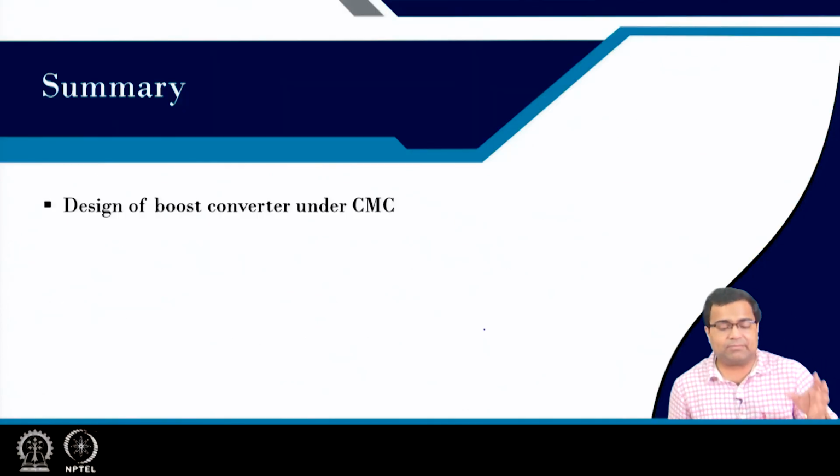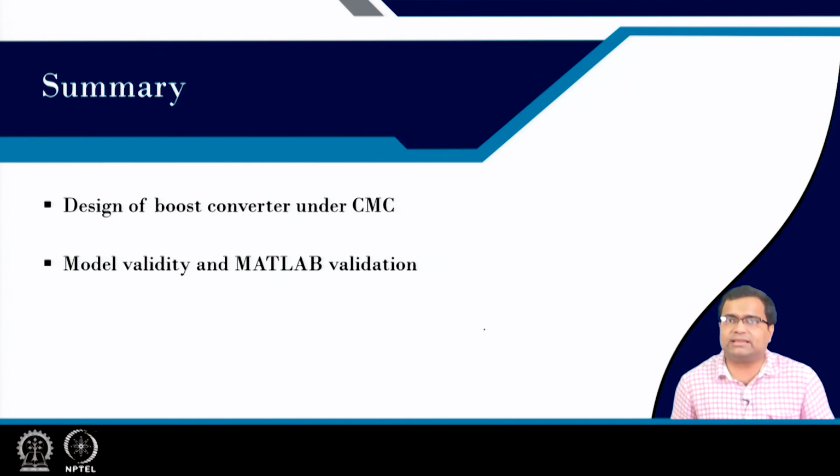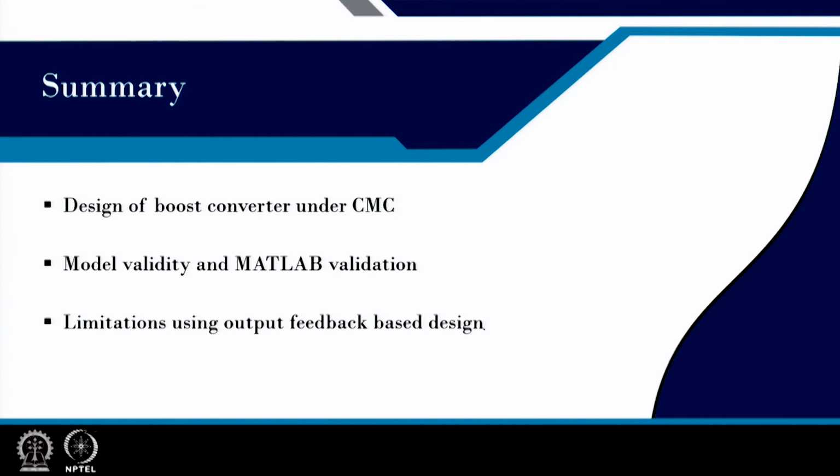So, in summary, we have discussed the design of a boost converter under current mode control. We checked model validity using MATLAB AC and transient simulation. We have discussed the limitation of the output feedback based approach. We have identified the trade-offs, and then we have discussed how to design state feedback current mode control using the state feedback based design approach.